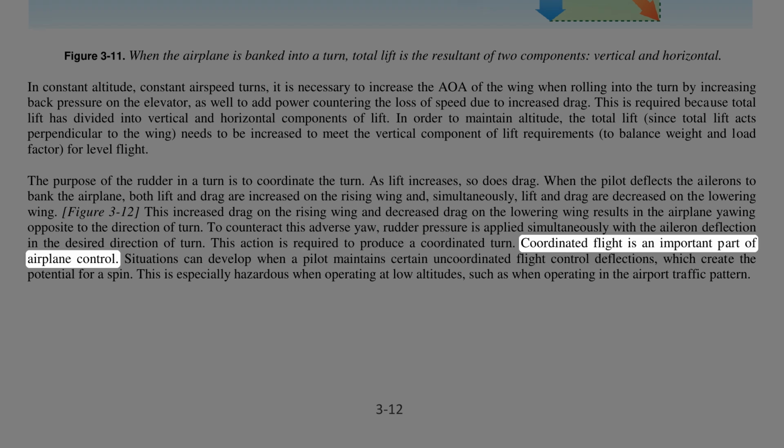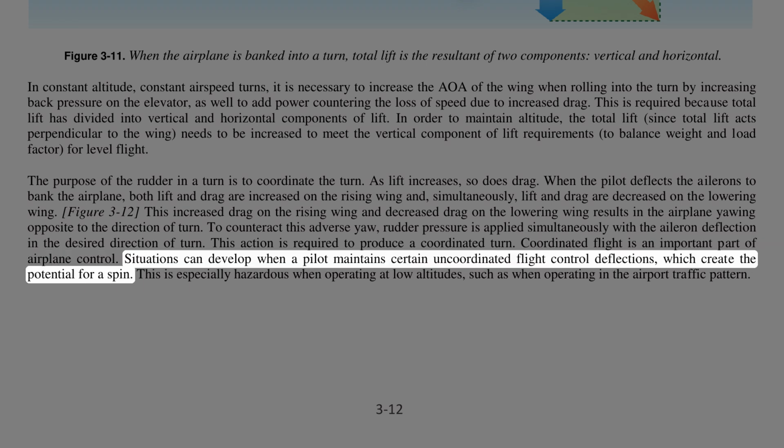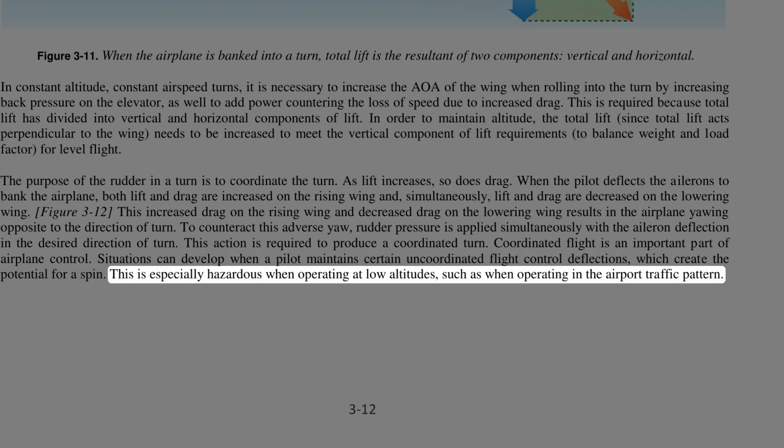Coordinated flight is an important part of airplane control. Situations can develop when a pilot maintains certain incoordinated flight control deflections, which create the potential for a spin. This is especially hazardous when operating at low altitudes, such as when operating in the airport traffic pattern.